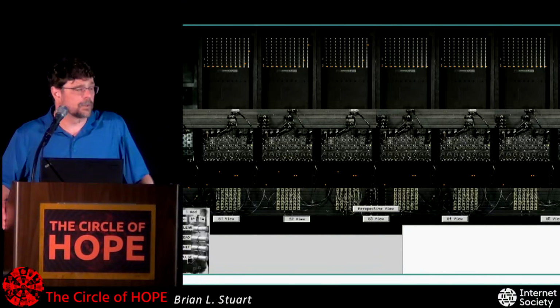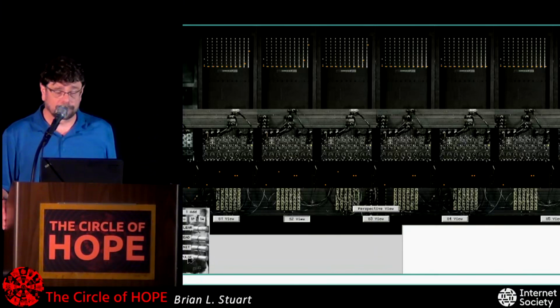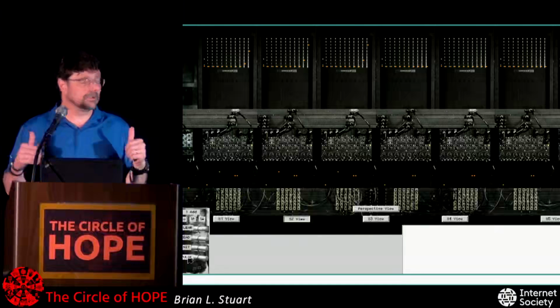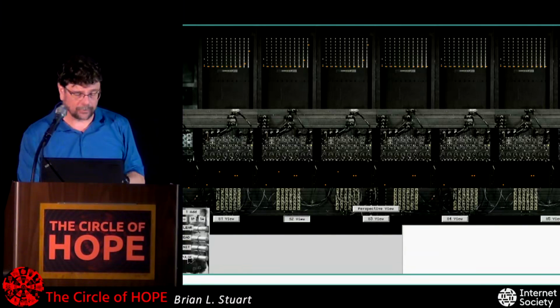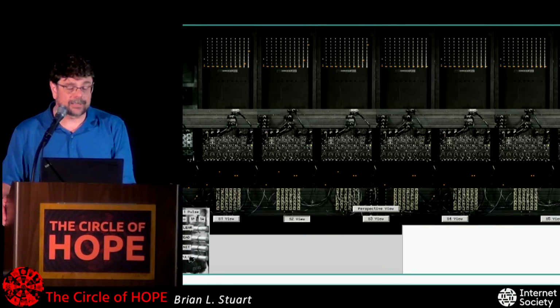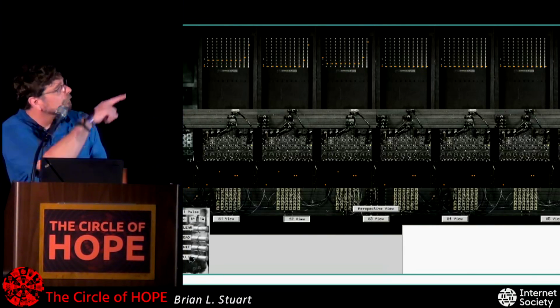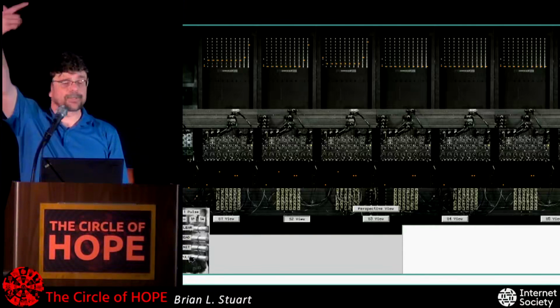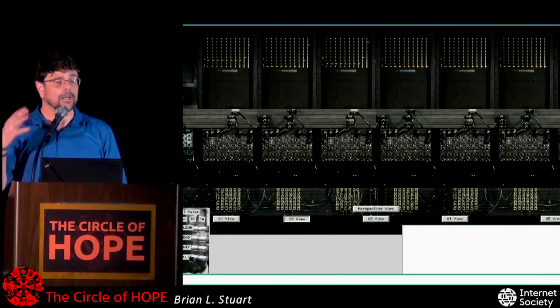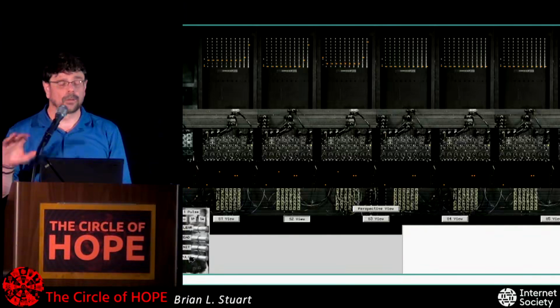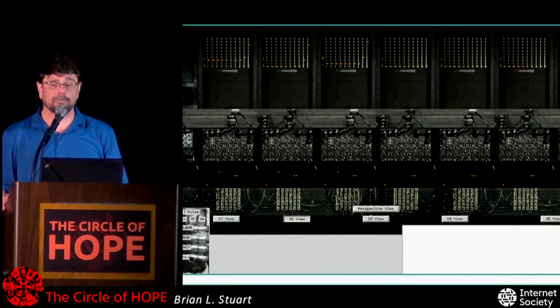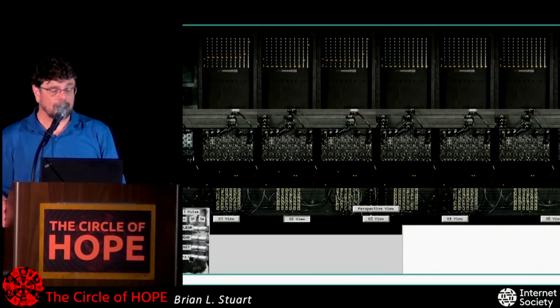Now, I've loaded the number 27 into the other 2 accumulators. So what I'm going to do is read out the value from the 15, add it to one of them and subtract it from the other. To do that, I'm going to switch the mode to the pulse mode so you can watch it happening one step at a time. And as I'm doing it, you will see all of the values in the first one moving up as they roll around to their starting point. Until a carry is set, they go to the third one. Once the carry is set, in whatever column that is, the pulses will go to the second one.